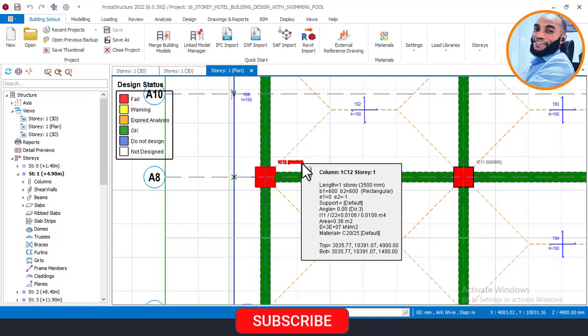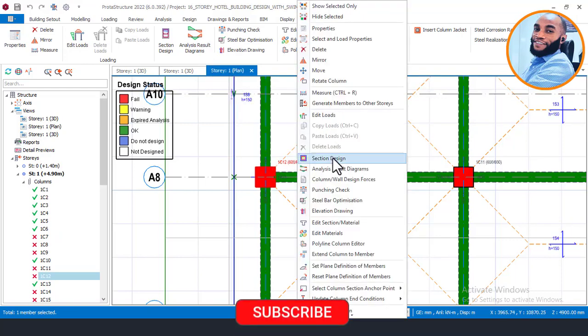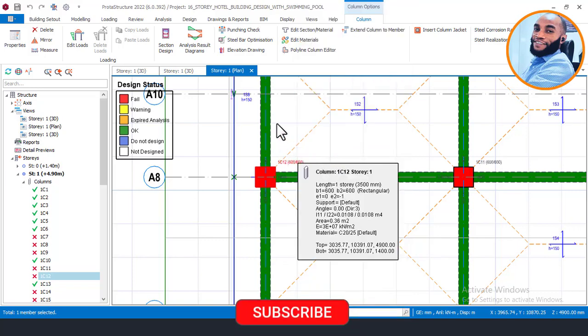Once this shows the interface, I'll click on that. So just click on the column, right click, and you will see this place that says section design. I'll click on this, and it needs to open up the column dialog for interactive design and all that. Let me just hold on for that to come up.